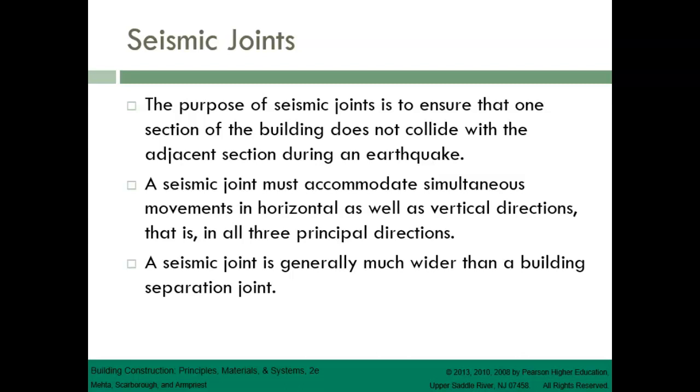So, the primary difference between seismic and building separation joints is that building separation joints primarily act laterally, where seismic joints have to be designed to act in multi-directions in all 3 planes. Seismic joints are also bigger than building separation joints.